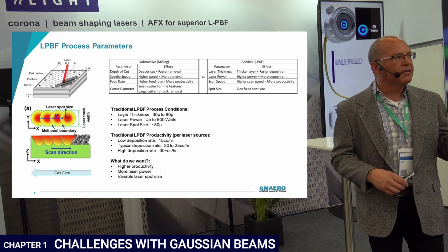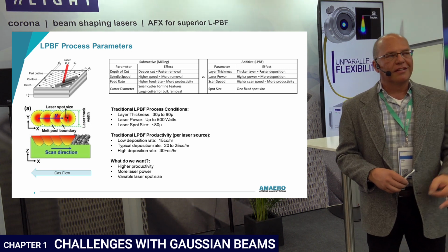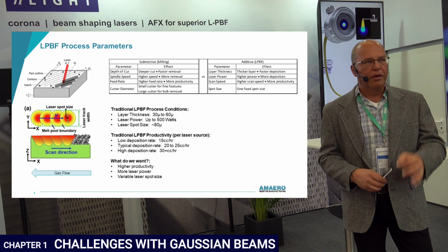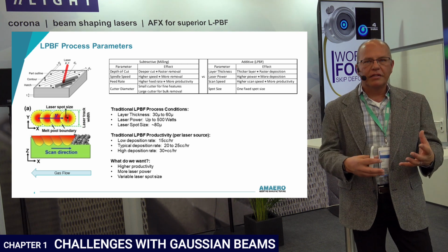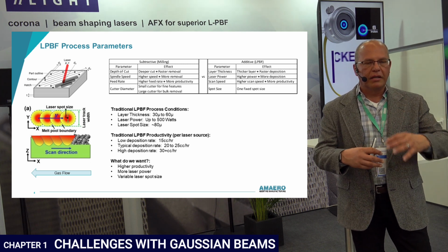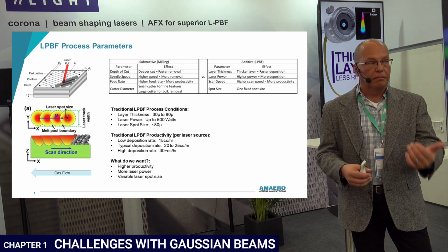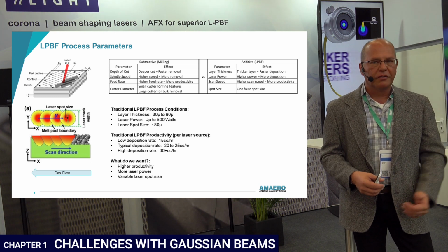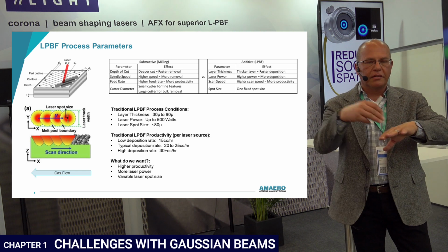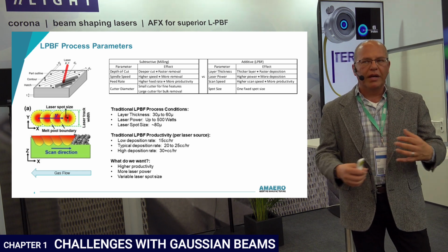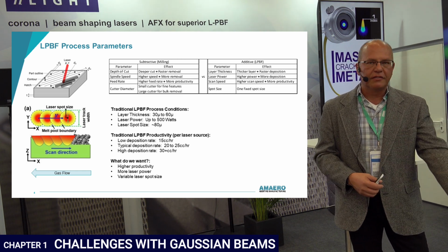We're not selectively laser melting. We are selectively laser boiling. We are boiling the metal, generating lots of vapor. It consolidates in the chamber in the form of very fine particles, submicron particles, pyrophoric particles. They are jumping around in the atmosphere. They're causing laser obscuration by getting in the way of the laser beam, which results in defects on the melt bed.